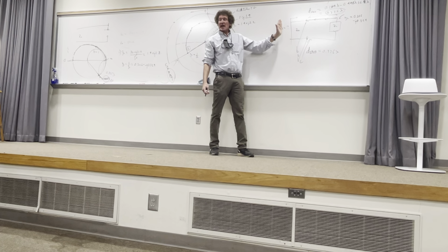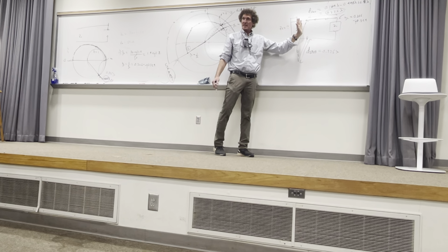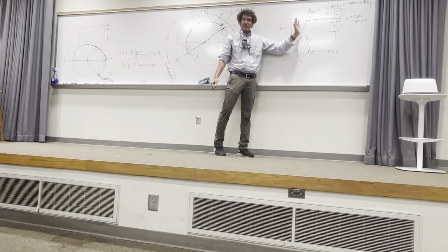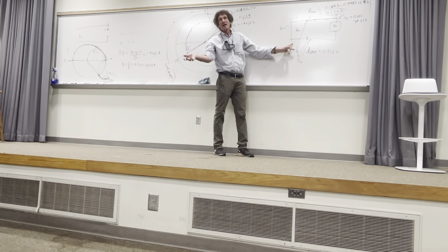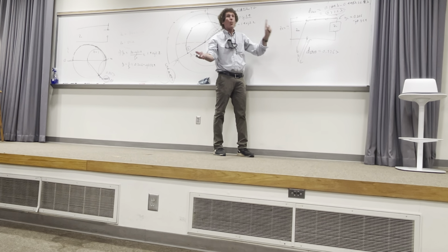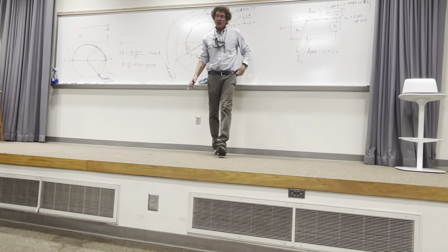It's got to be Z naught, right? Because the reflection coefficient is 0. The whole idea of connecting this stub is it'll make everything on that side of the stub connection look like Z naught, so you get no reflected wave. Your reflection coefficient is 0. Now, over on this side, what is the reflection coefficient? 0. What would the standing wave ratio be? 1. I'm just trying to make sure you're clear on that.